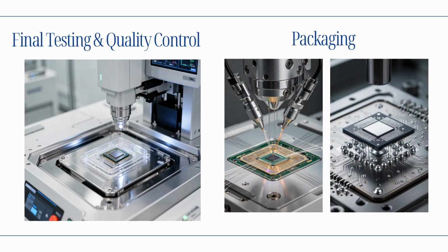Packaged chips ensure safety and functionality, providing essential electrical connections for efficient operation in various applications. There are broadly two different types of packaging, namely wire bonding and flip chip. However, there are quite a few innovations going on in this field in recent times.